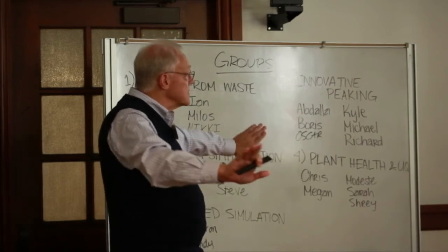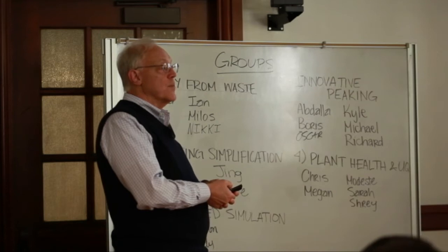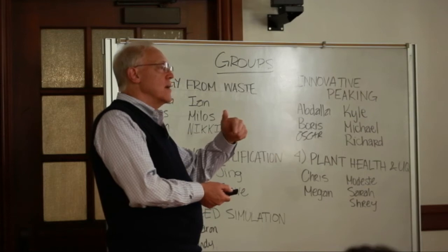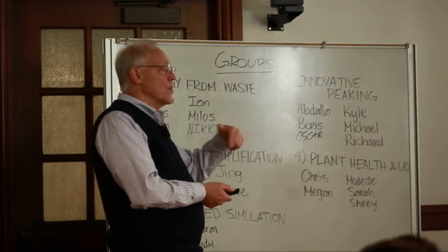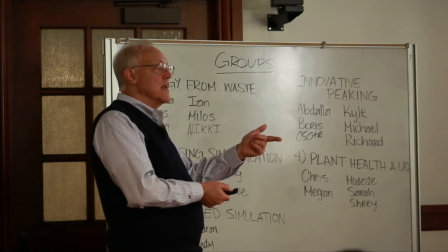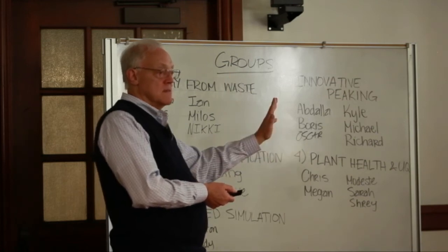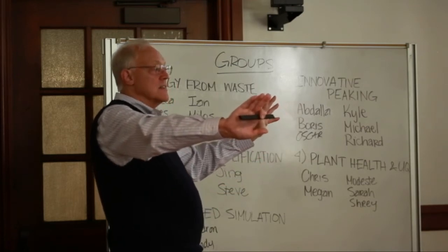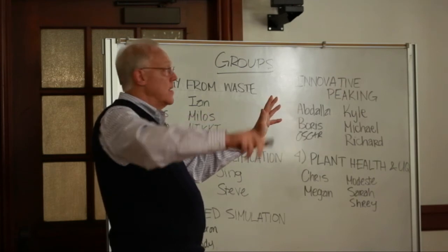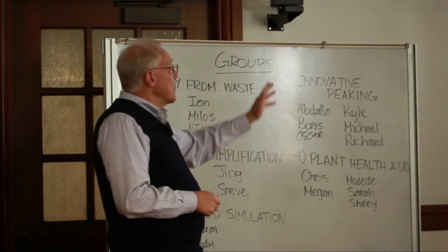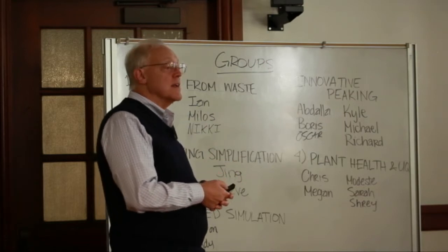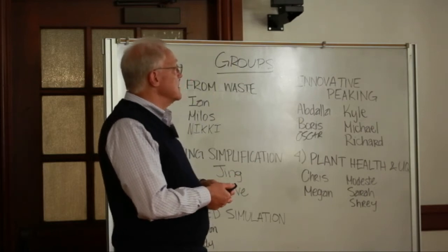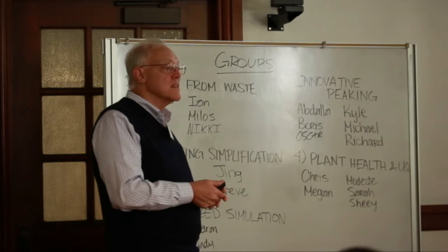Keep the primary and secondary sides functionally separate. This gets in part to, it's both a regulatory consideration and a practical business consideration if we're going to cogenerate. I want the ability to separate my plant from the petrochemical plant, as an example, so the reactor doesn't see the effects of that plant. And there are provisions for severe accident backup cooling and containment control if that's necessary, if I haven't already eliminated that as a detail. And I've got a tool down here, a systematic risk analysis.